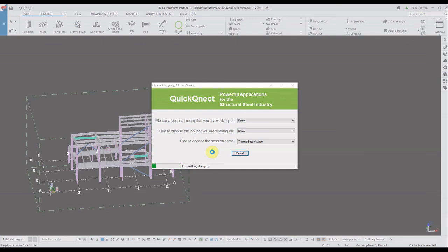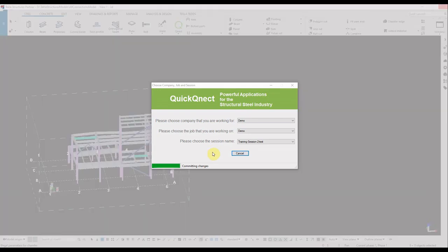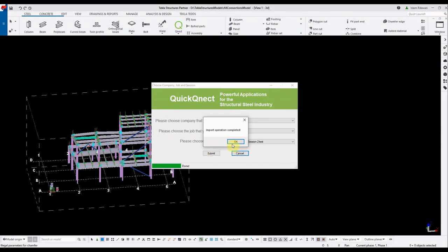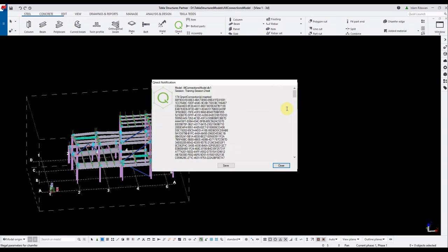Those are also transferred to the beams, so that if you want to show them in drawings or reports, you can show the capacity of the connection and also the connection code associated with this connection. The connection code is also visible in the reports showing calculations, so if someone is reviewing it, they can refer to it easily. So here are the connections inserted.